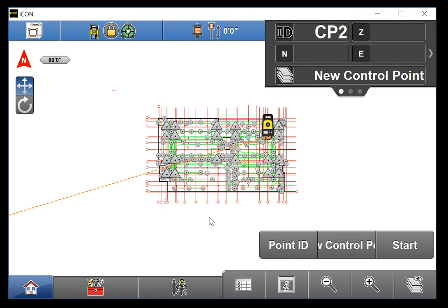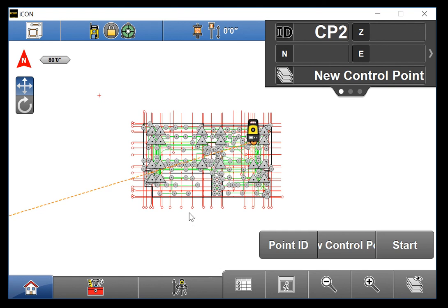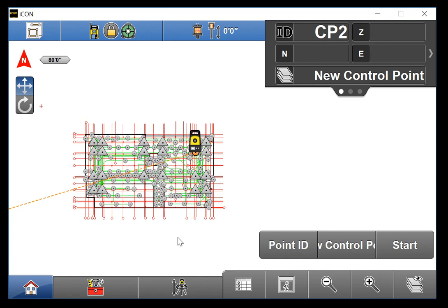If this is a typical floor and is guaranteed to occur on every single floor, the easiest thing to do is jump into as-built, put the tip of the rod on top of the sleeve, and level up. Set your point ID, code, and symbol, and then store that one sleeve like this.